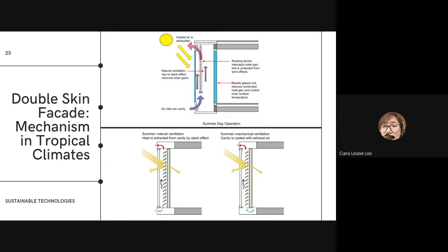So this can be used to reduce air conditioning usage and lessen heat gains in the warmer regions of the site for the proposed bus terminal. And double skin facades are bioclimatic technologies, as I mentioned a while ago, and they're also used in many buildings, such as the Gherkin in London, which was designed by Norman Foster. This technology mainly relies on external factors such as solar radiation and external temperature that directly impact internal comfort and quality of life of end users.